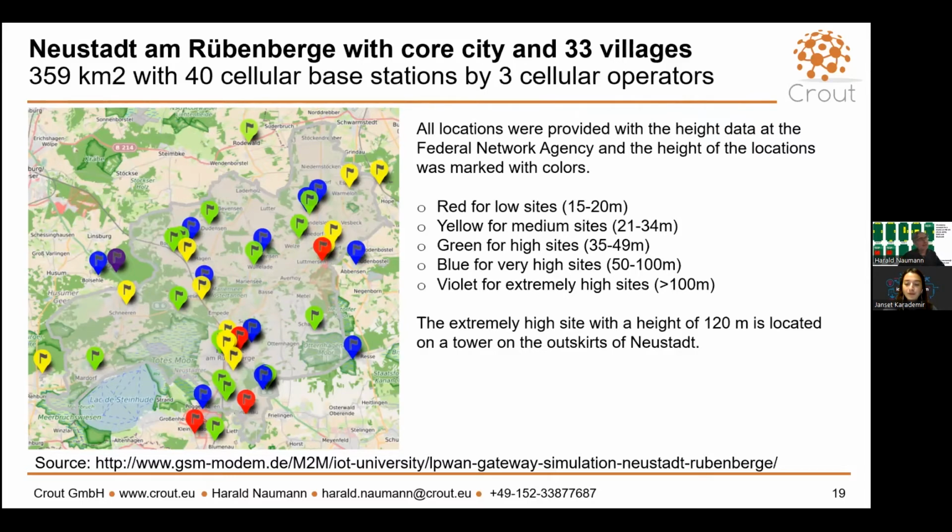At LoRaWAN, we have in the data sheet a sensitivity of minus 137 dBm. What people don't read is that LoRa can receive 20 dB under the noise floor. The noise floor is in the near of minus 100 dBm. That means at nearly minus 120, minus 112 dBm is the limitation. If you read some studies, the minus 137 you reach only in the laboratory. It means the real link budget of LoRaWAN is estimated 15 to 17 dB lower than on the marketing slides. So there is a difference between marketing and reality.